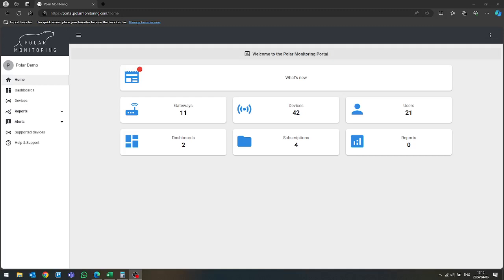Today I'm going to be taking you through adding and setting up of your own registers on the Polar Cloud. This is to be used for all devices or all systems that are not currently supported on the Polar Cloud. We've actually built the framework and everything you need to map those registers yourself and bring on anything you would like that has Modbus RS485 into the Polar Cloud. Okay, so this includes non-supported power meters or non-supported devices, as well as your PLCs or certain devices that are one-off type applications.